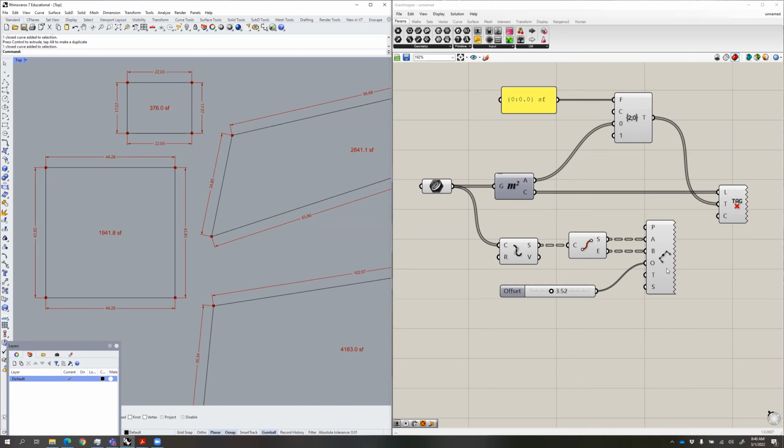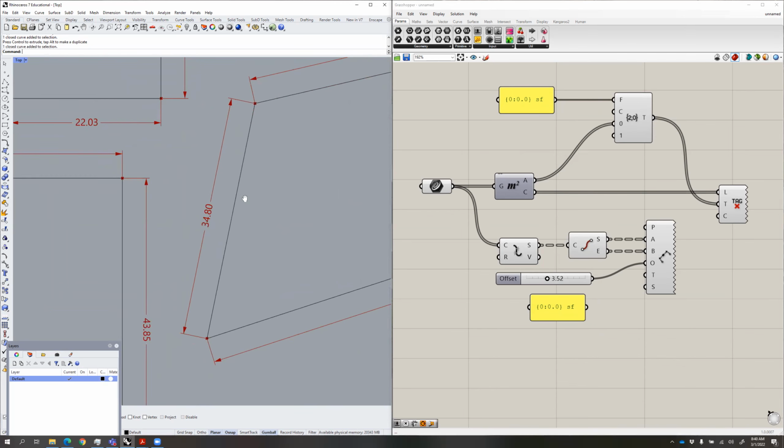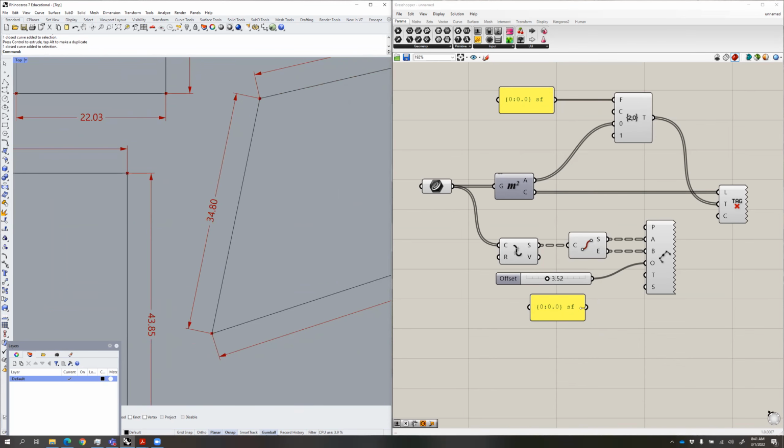Okay, so we've added that dimension now, and then the last thing that we can do is two last things. You can also change the format of it. Again, right here we have a format tool. So quick thing you could do, you can just take a panel that you've already written, copy and paste it, right? And we can format these dimensions. Let's zoom into a dimension here, just see what happens. And let's do 2 decimal points, and let's add a little foot mark right there.